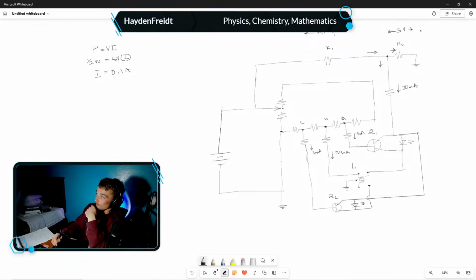So now we've determined that I need 5 volts across here, 4 volts across here. Is what I want to do. Yeah, 5 volts, let's keep it at 5 volts. I don't know, I could say 6 volts. Should we do it? Let's change it to 6 and 3. For the purpose of any imperfections, perhaps I want to have a little more voltage disposable. So 6 and 3 is going to be our ratio.